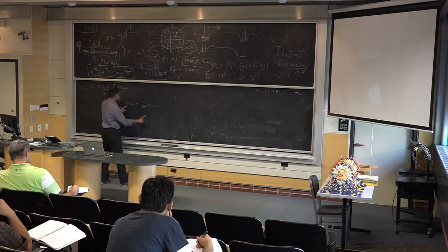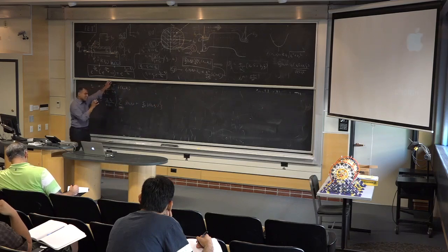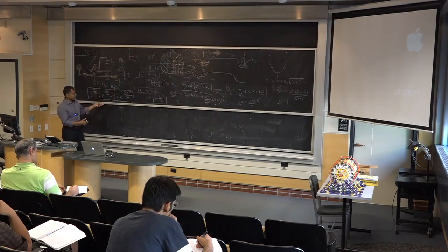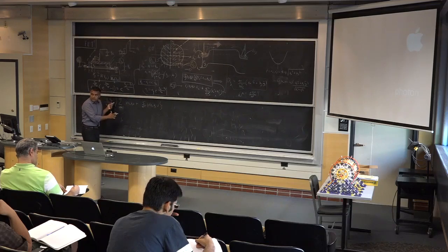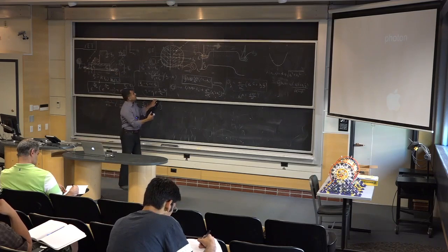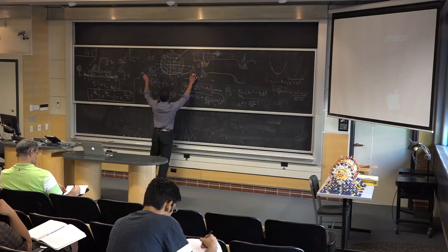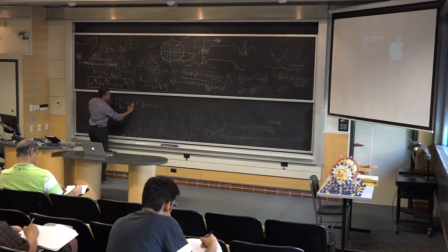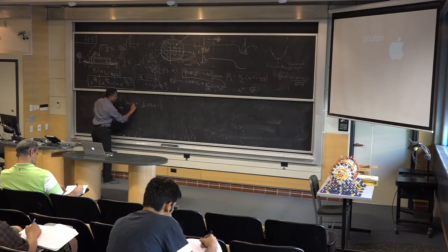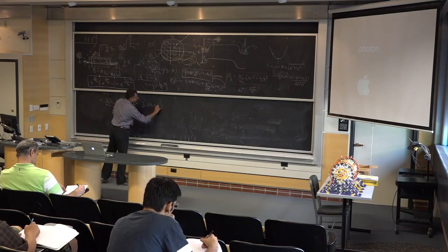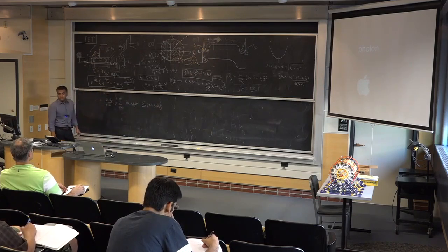But I think you will agree with me that these two f's are actually not necessarily the same. If I apply a drain voltage, they can be different. Why? Because these functions are still Fermi-Dirac distributions. But the Fermi-Dirac distribution is completely determined by the Fermi level, right? And the Fermi level for the right-going carriers is of the source, and the left-going carriers is of the drain. That's the difference. That's the only difference, actually, which means that I should write here for right-going carriers, these are in equilibrium with the source. So the Fermi level for that is the quasi-Fermi level of the source. And this is the Fermi level of the drain. So that's really the main difference.